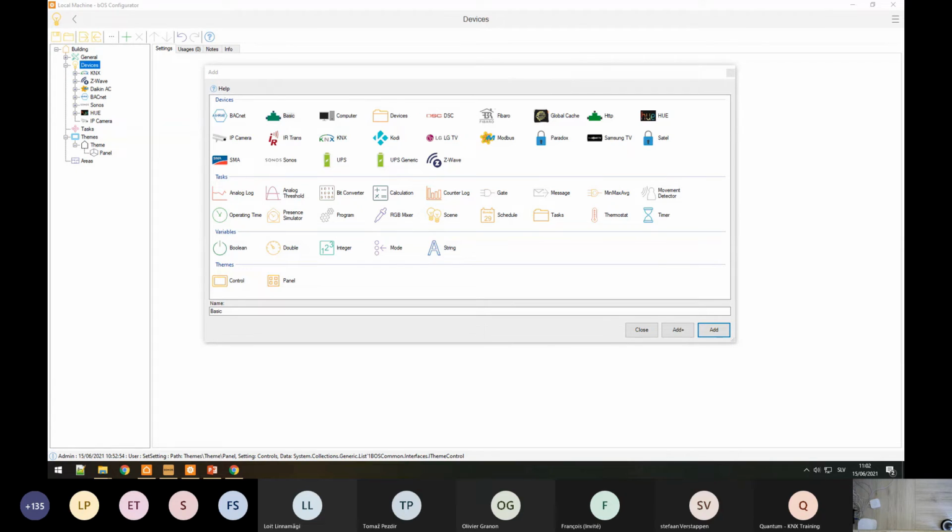So you can keep the questions coming, and we'll try to answer them after the training. So Z-Wave dongle will have to be connected to PC or Jigsaw. Z-Wave dongle can be connected to both, basically. If you have the dongle, and if you want to have both KNX and Z-Wave, you can then plug the dongle to either the PC or the Jigsaw. It will work on both. If you have the Colibri server that we have, which actually has a Z-Wave dongle or gateway built in, you don't even need the dongle. You can just use the Colibri as a Z-Wave gateway.